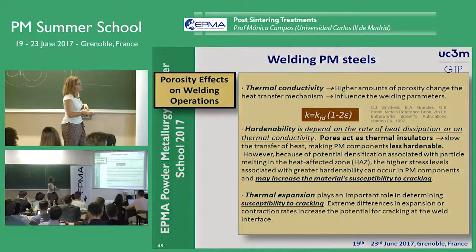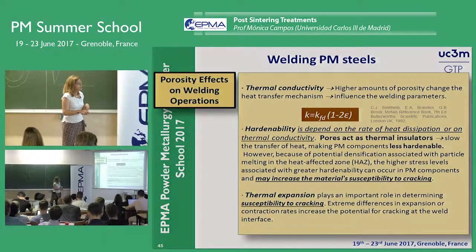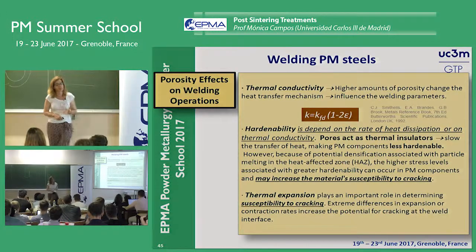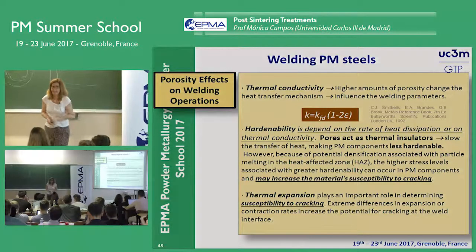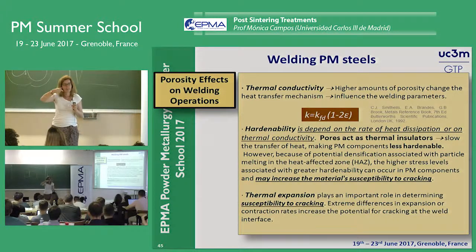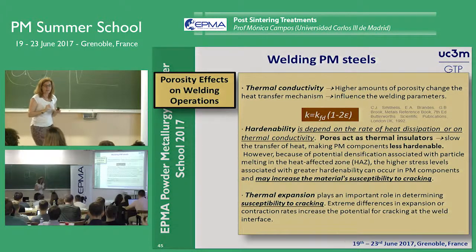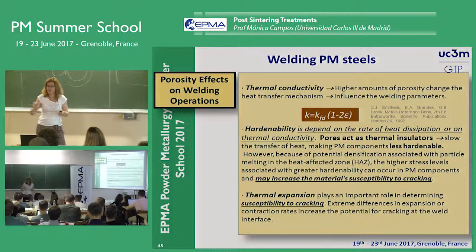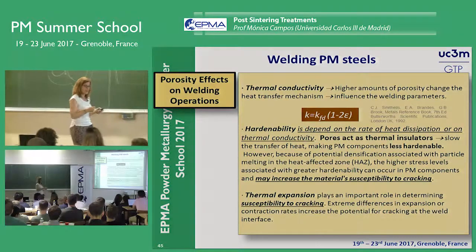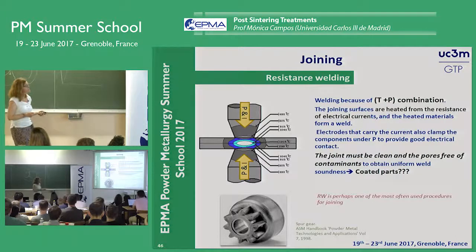Of course, it also conditions the thermal expansion, and then we can determine the susceptibility to cracking. Then porosity always makes another level of difficulty when we are making joining processes, as well as what happens with the machinability. The pores give us an extra level of difficulty in the processes.